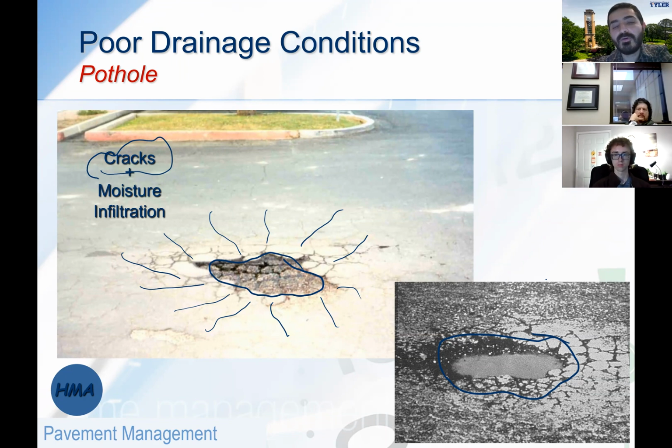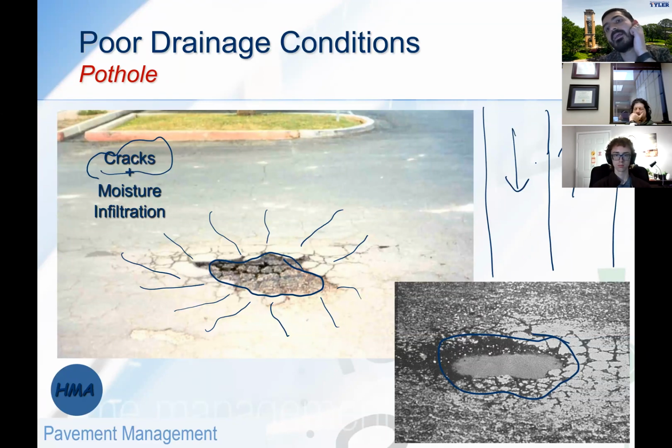One of the reasons for having potholes is poor compaction during the paving job, mainly on the edges of the right lane. Let me try to draw this condition for you. If I have a two lane roadway, one lane per direction, and we're doing a paving job, sometimes if it's just one lane per direction, we try to pave it all at once with the paver, especially if the width of each lane is somewhere between 10 and 12 feet.